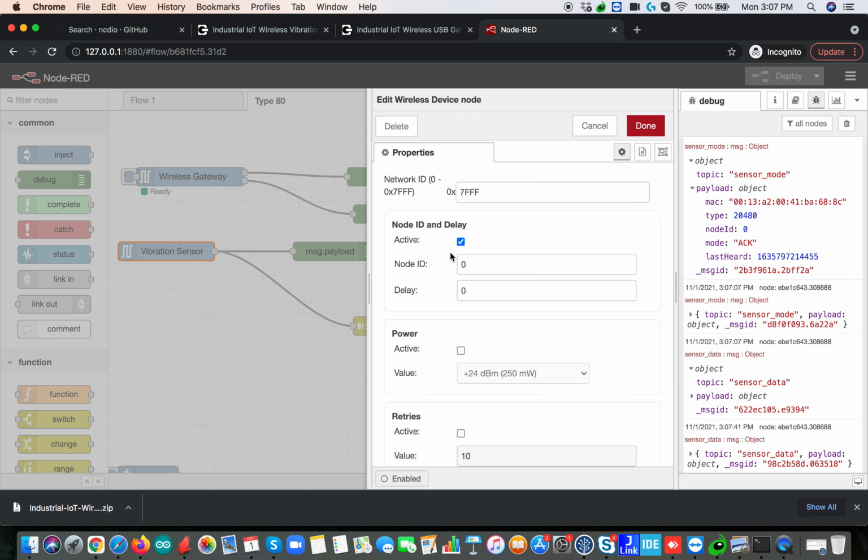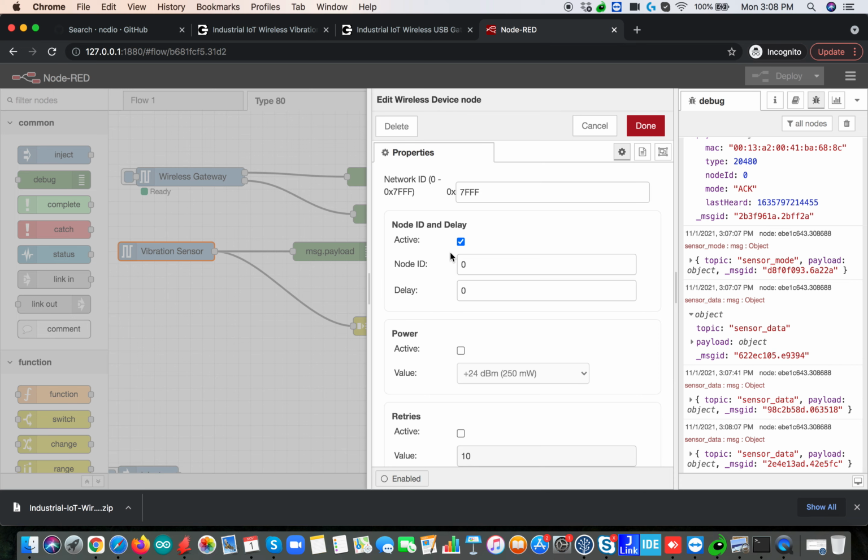If you have only one receiver, you can run into RF issues. So what we did to avoid that is, if you set your node ID from 0 to, let's say, 10, then what will happen, the sensor with node ID 0 will send data first, then 1, then 2, 3. They will space out evenly to make sure everybody is getting some room on the RF and sending the data. So this is why it's very important.